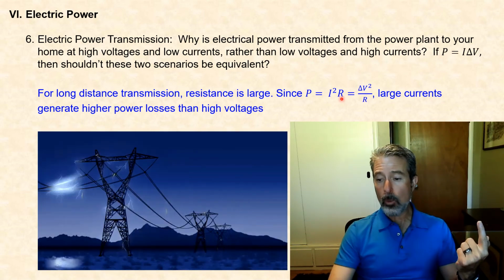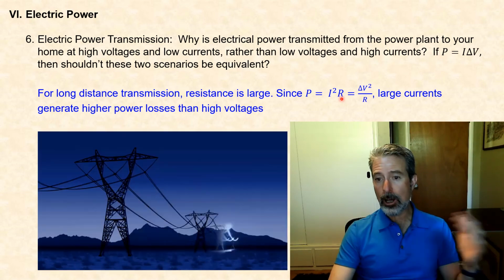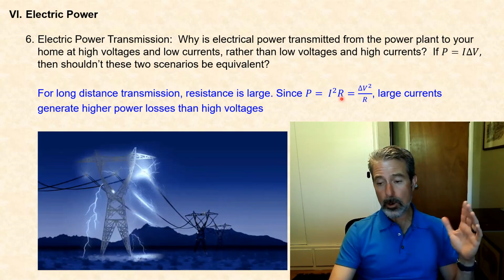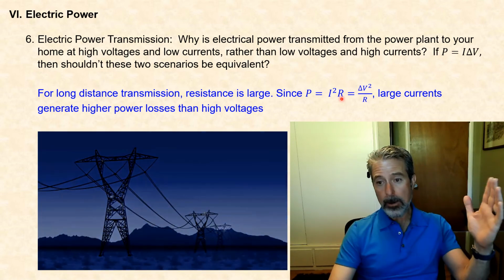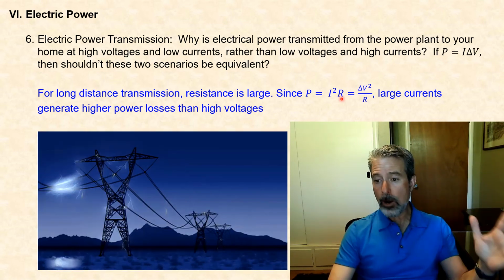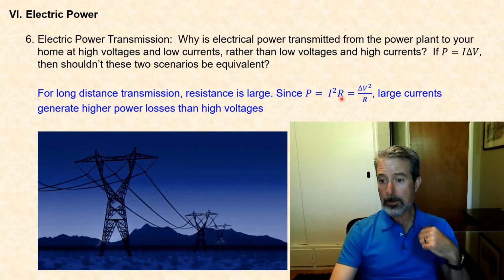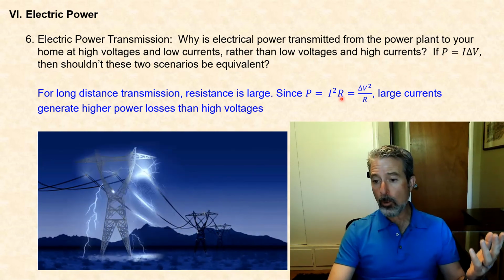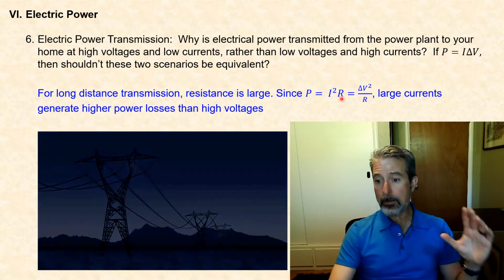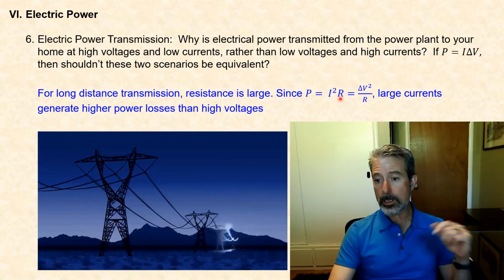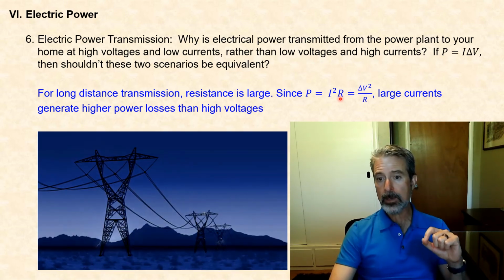Think about it, these copper wires can be many kilometers long, and when this is the case, the I squared R power loss, by the time that power goes from the power plant to the homes through many miles of copper wires, very often about 40% of that electrical energy can be wasted in the form of thermal heating.